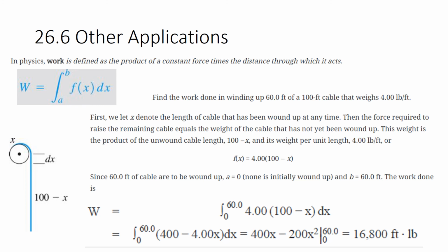Remember, work is the total amount of work, and then power, which is many times what motors are rated at, is how fast you can do that work. So first I need to know how much work I need to do, and then I can buy the right horsepower or foot-pounds per second power to decide how fast I want to lift that cable to the top of, let's say it's a stadium or an arena, and getting set up for a show.